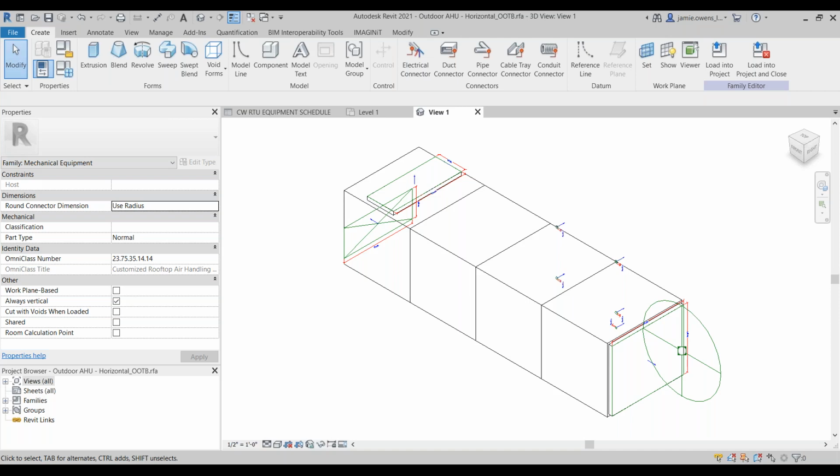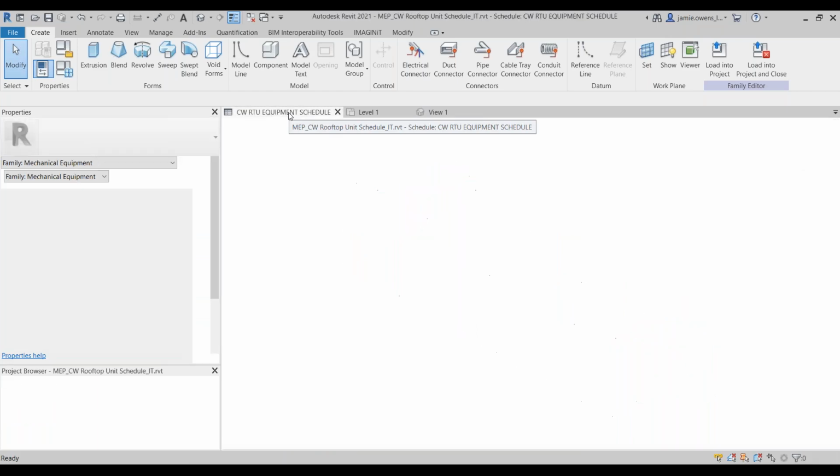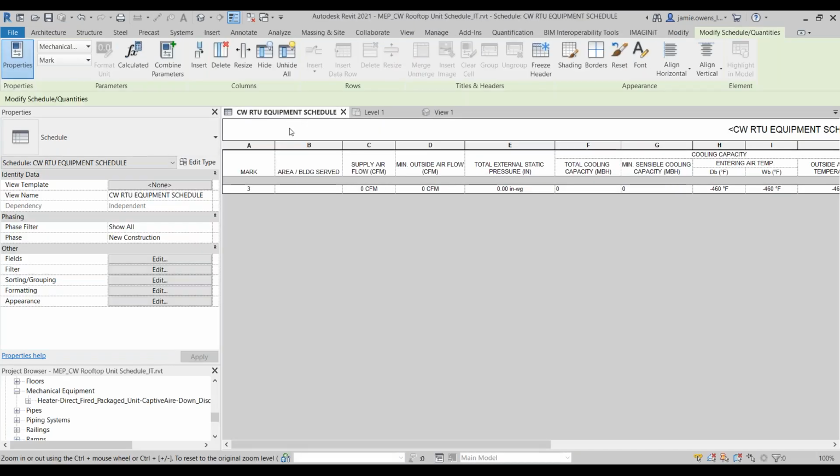Okay. Can I add parameter data to all types of families at once? Not quite sure of the question. We can add the parameters. If we add the parameter in a project, we can add it to all the categories, which becomes a project parameter, but then that becomes a bigger challenge.